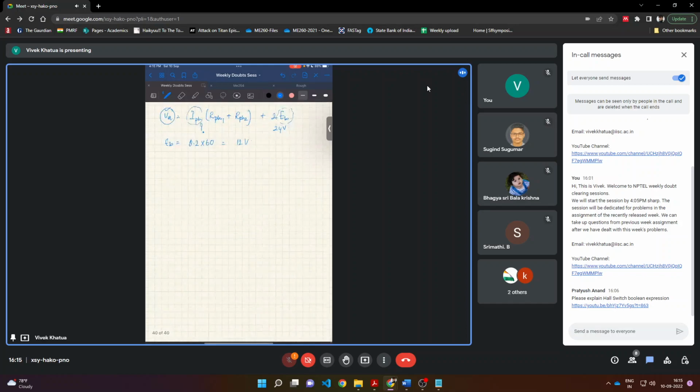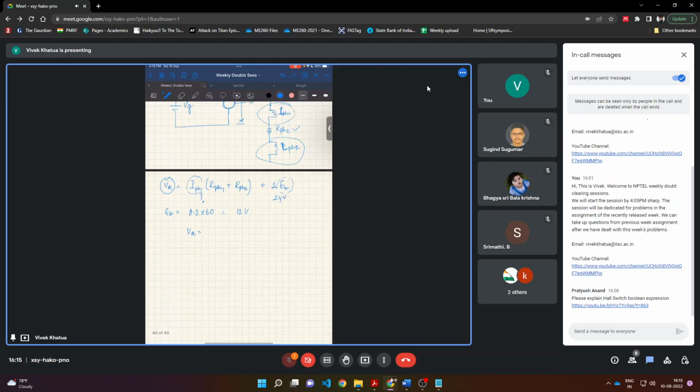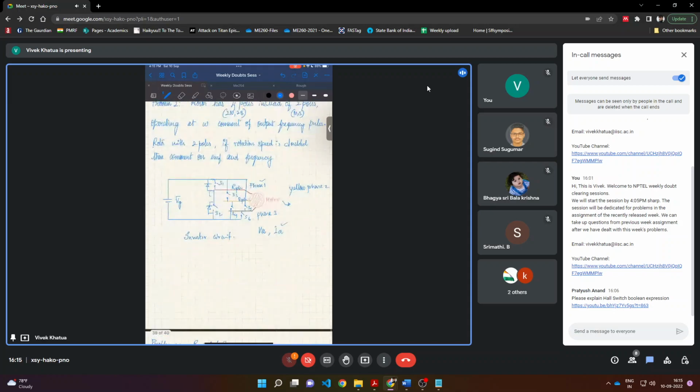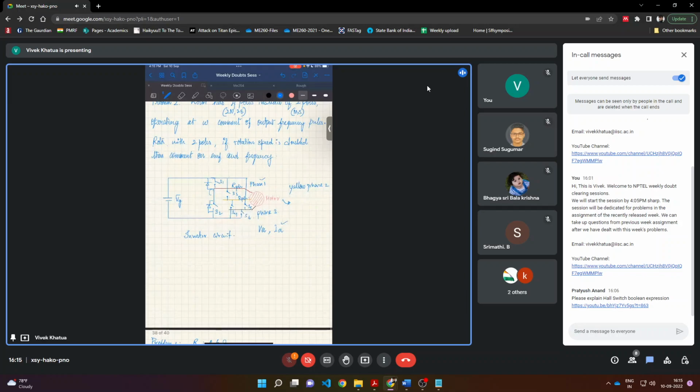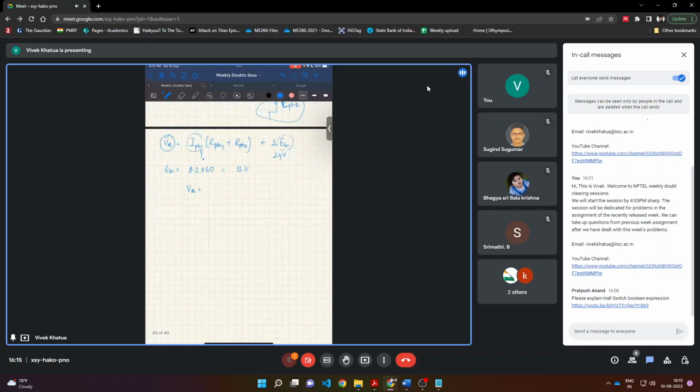So we'll go back to the previous lecture, where for such a circuit with two legs, you will have an effective voltage of (2D minus 1) times V_G.